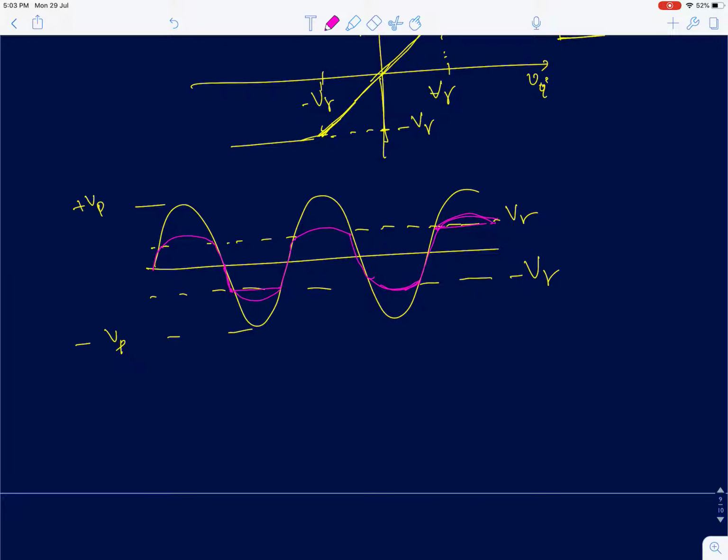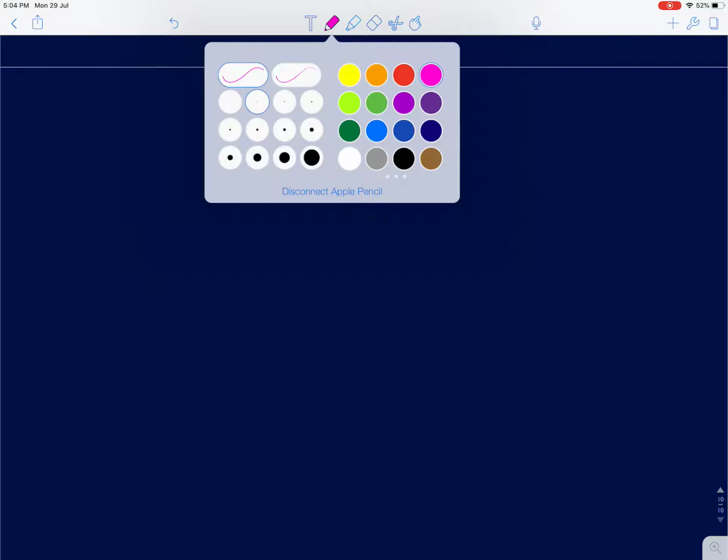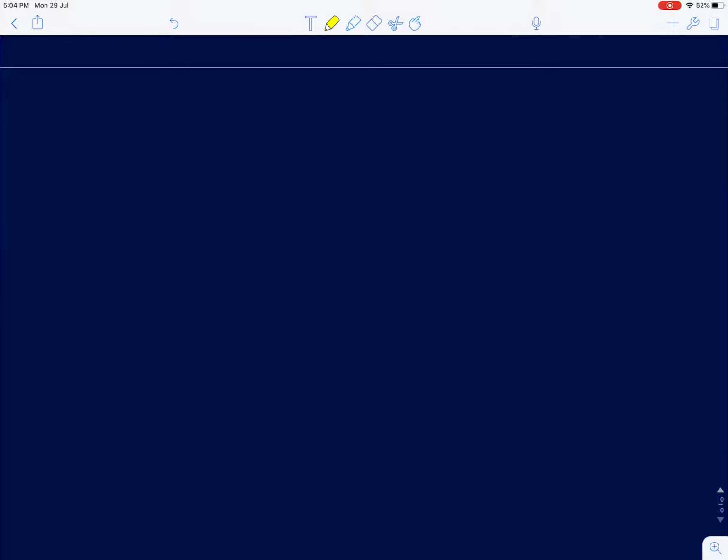Now why do you get that? So that we will try to analyze. This diode model doesn't capture this small variation. As we discussed, when we use a cut-in voltage model, of course, it makes the analysis very simple. You can just use hand calculations. It's extremely simple to analyze circuits using the cut-in voltage model. But then it doesn't capture small effects.